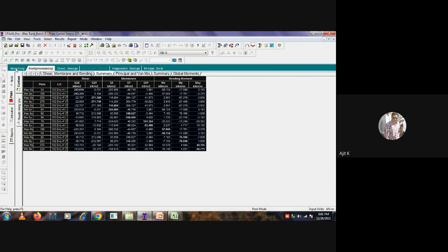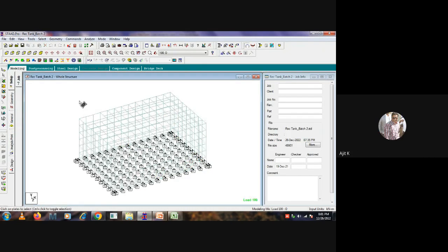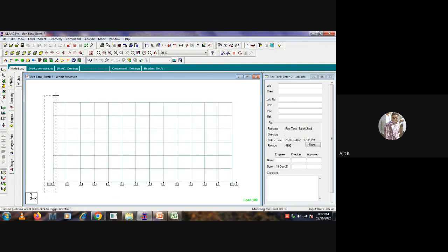Sir, I have one doubt. While applying the load, like a soil load which is acting on the walls, in the plate loads where I have chosen hydrostatic and selected the plate, in that case why are we selecting interpolating along the global axis? Why? Because that pressure is acting in the x direction actually.